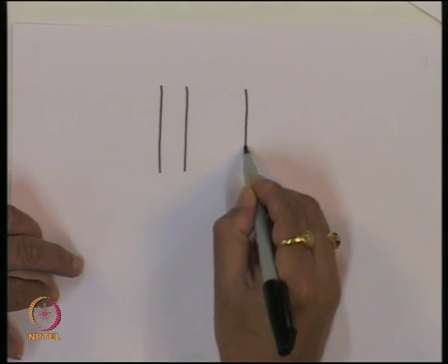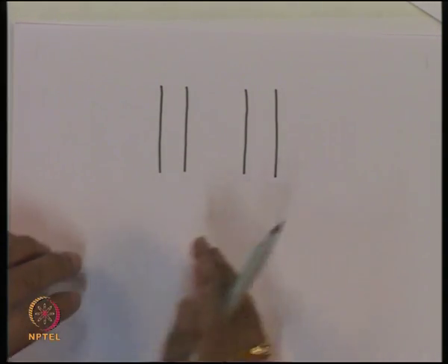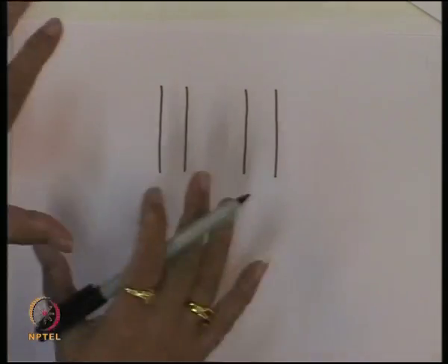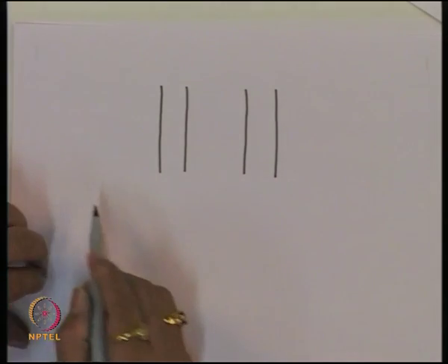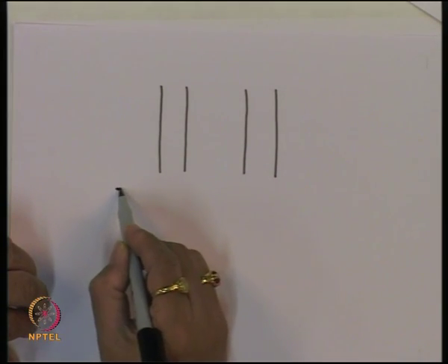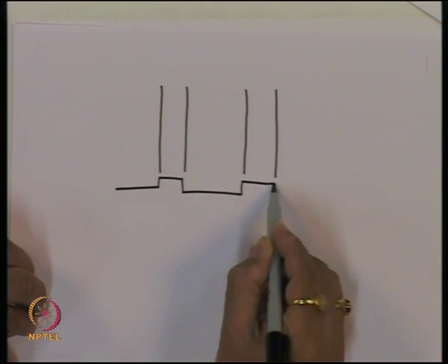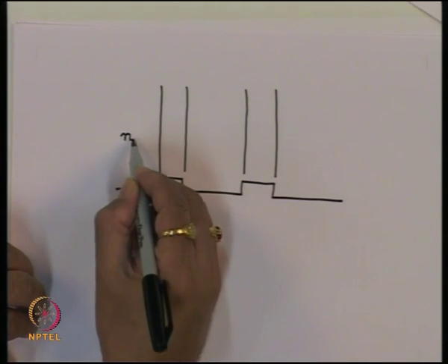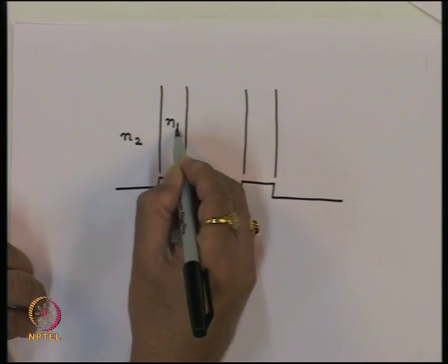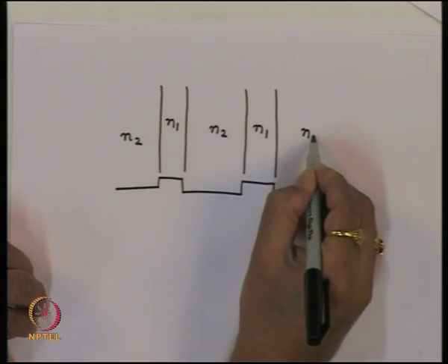These are two channel waveguides. Instead of considering these two structures like two waveguides, we can say we have a structure, composite structure, for which the refractive index variation is this. This is what channel waveguide essentially does. You have a refractive index something here N2, you have a refractive index here N1, here it is N2, here it is N1, here it is N2.